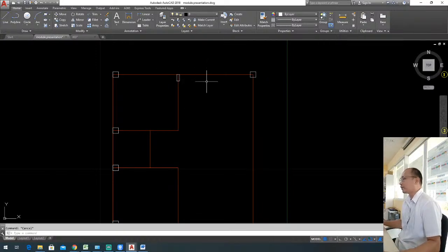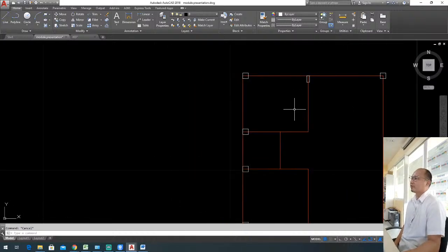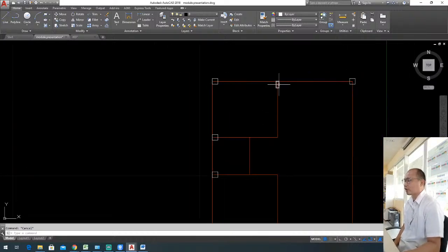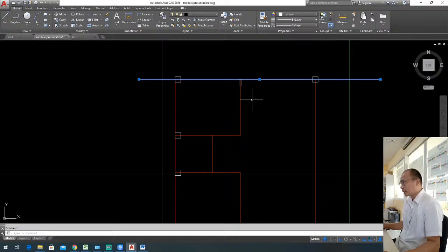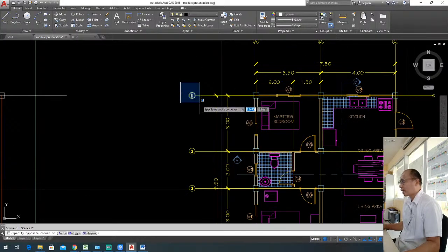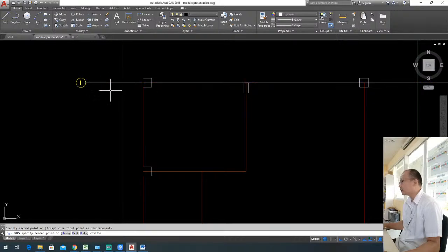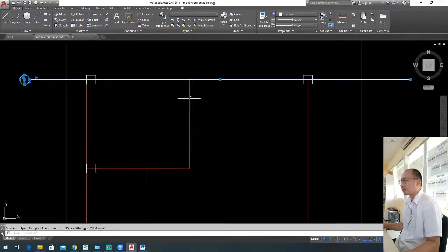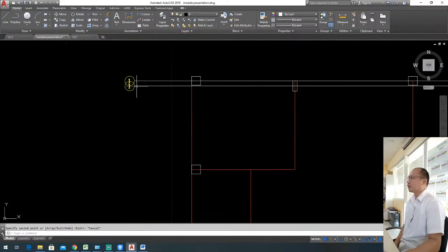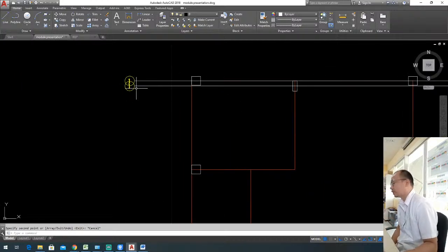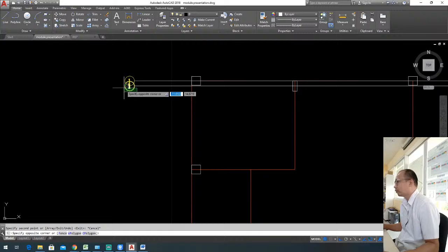What about this type of column right here? You have a column right here and you've got a column right there. So by the time you provide the column balloons, and then you have a column balloon here, by the time you copy this one, there would be intersection. This is the possible problem we have.